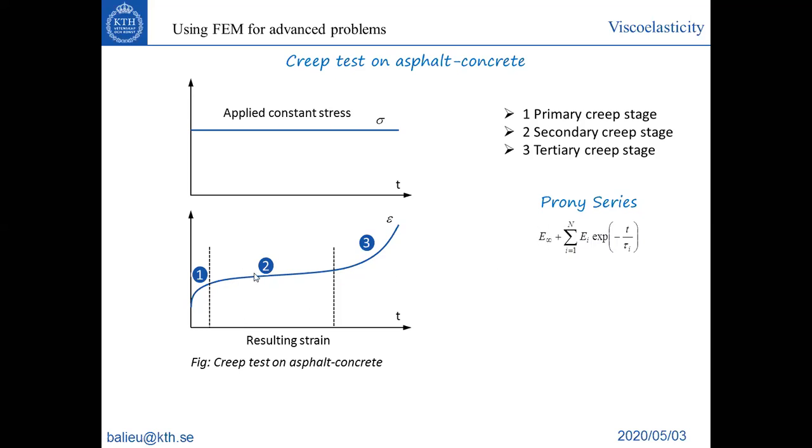If you wait a sufficiently long time using this Prony series, the stress will be linearly proportional to the strain, and the relation between stress and strain will be E infinity, which does not depend on time. So for a sufficiently long time, you will have after a while a flat curve.